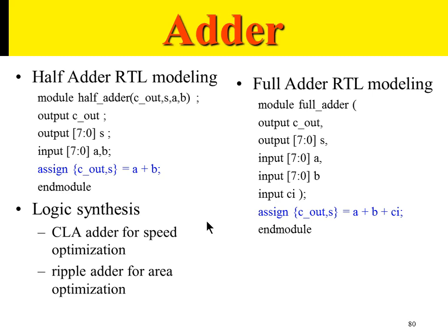So what that means is, if you're optimizing for area, you're telling the synthesis tool to create the smallest design possible without changing the functionality, obviously. Or if you say optimize for timing, you're telling the synthesis tool to create the fastest design possible out of the Verilog code that you have written. You're giving the Verilog code as an input to the synthesis software. At that point, you can optimize for area or you can optimize for speed.